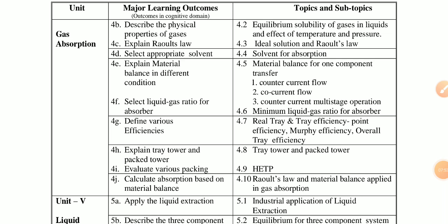Now the gas absorption. Simple concepts and some applications we will see. Describe the physical properties of gases. Any physical properties we will see. Then Raoult's law, Henry's law. What is Raoult's law? Raoult's law equation is: partial pressure is equal to the vapor pressure multiplied by the mole fraction.